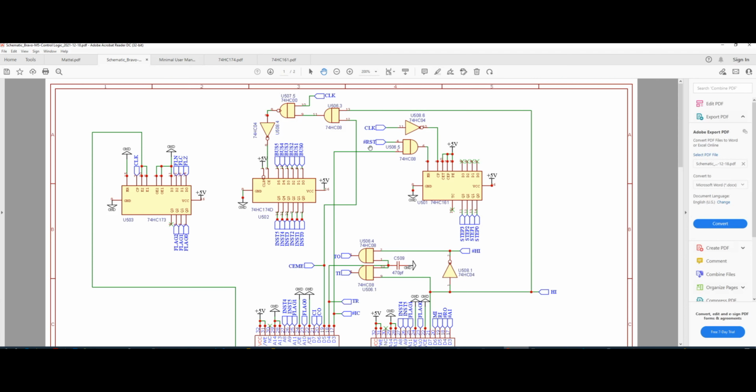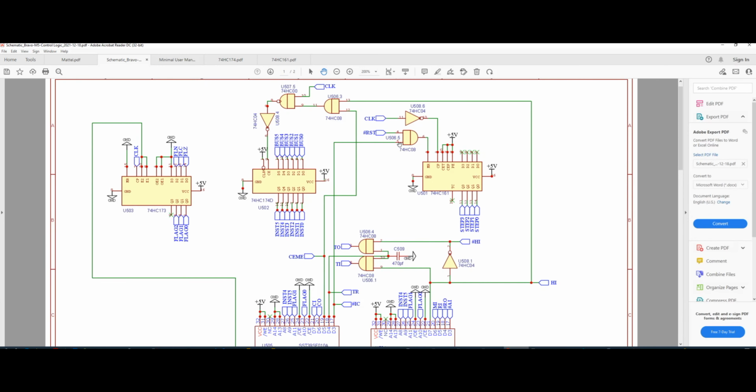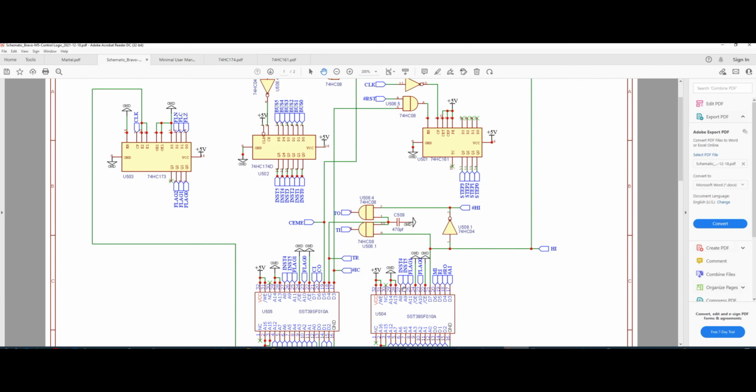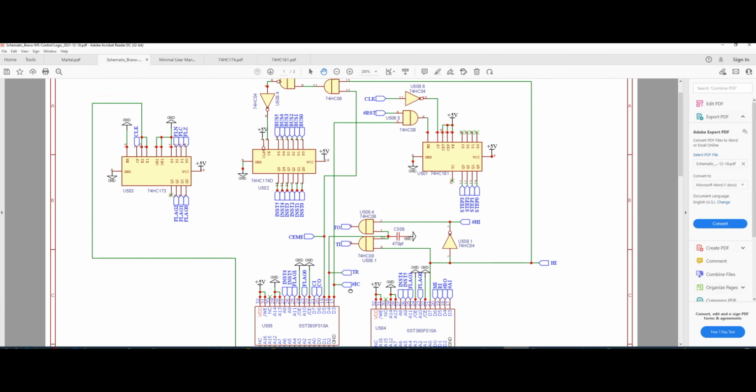So the first signal that is coming to this AND gate is our main reset signal for the computer. And our main reset is active low, so whenever we want to reset the computer, we need to bring that signal low. However, in a normal situation, that signal is high. Therefore, one of the inputs to that AND gate is high. However, the other one, as you can see, is coming from the output of our control ROMs, and specifically this signal is called IC.